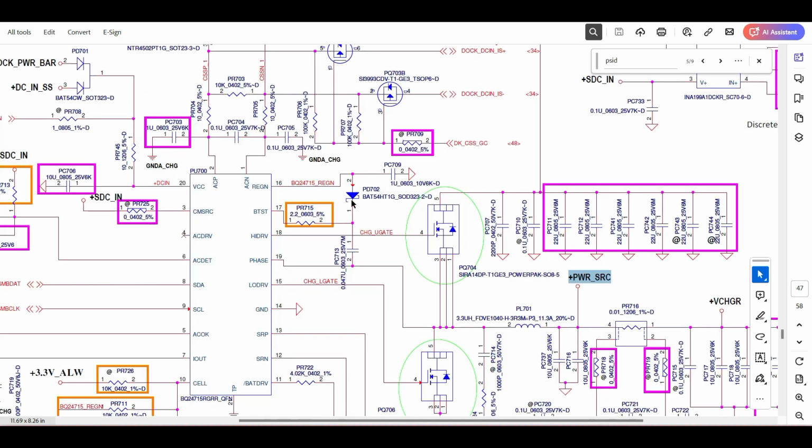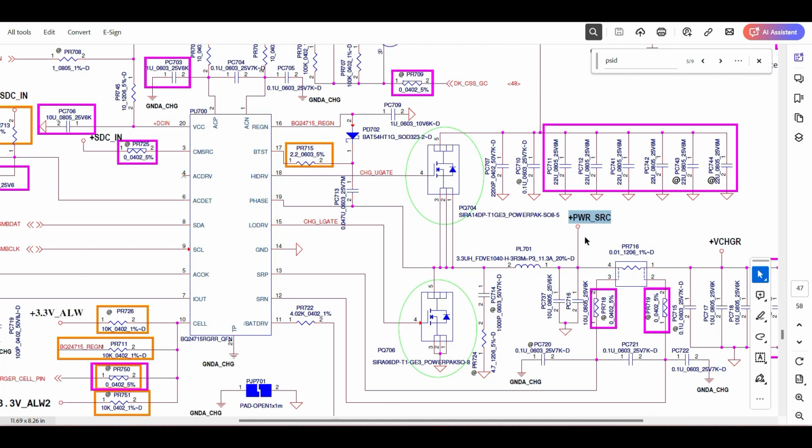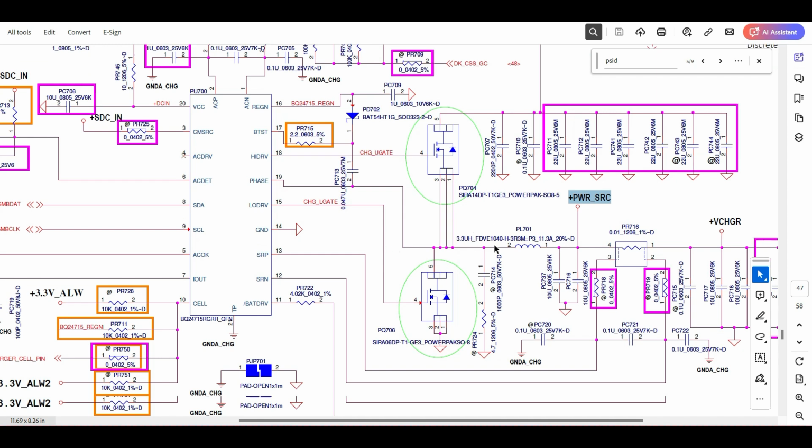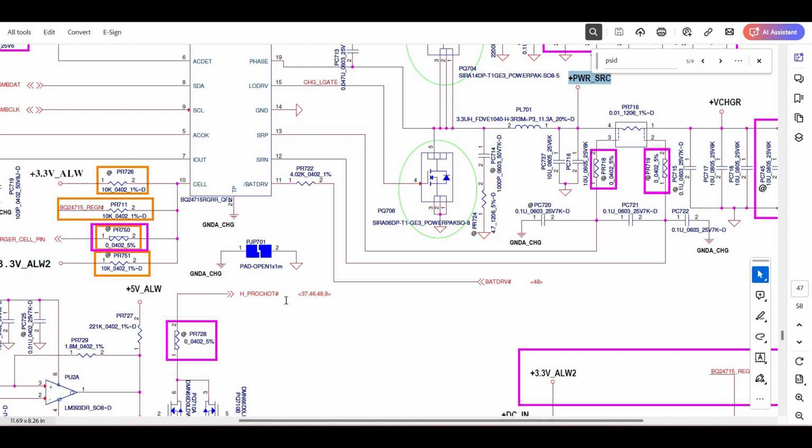In some cases, some technicians will be finding out this CLR voltage. They will directly inject some 19 volts to some other step down ICs and all. So they will make the board more complicated. But the simple method is, here you need to check the battery voltages. The battery side voltages, whatever are there, those have gone all over the motherboard. That is the major difference here.